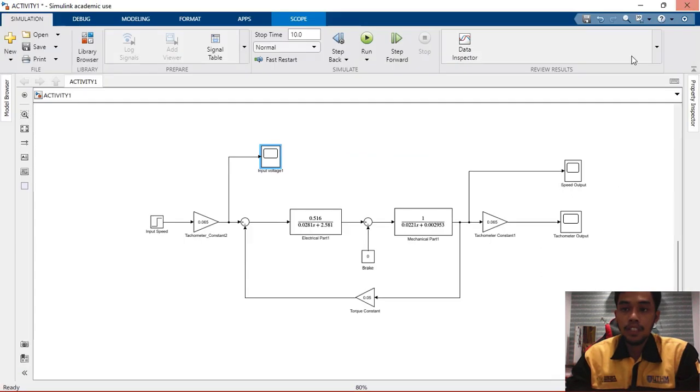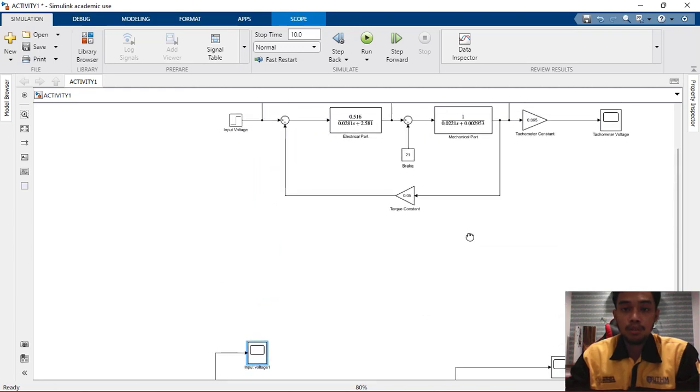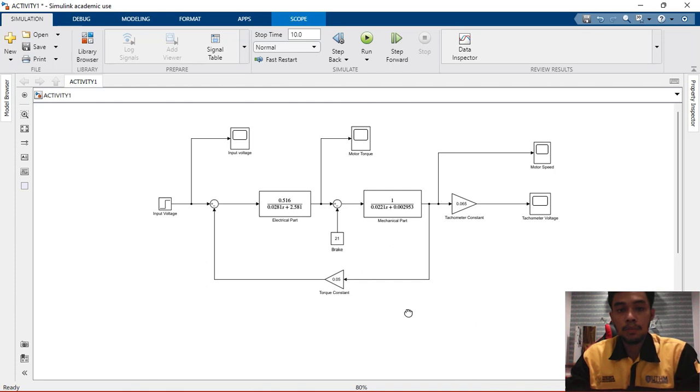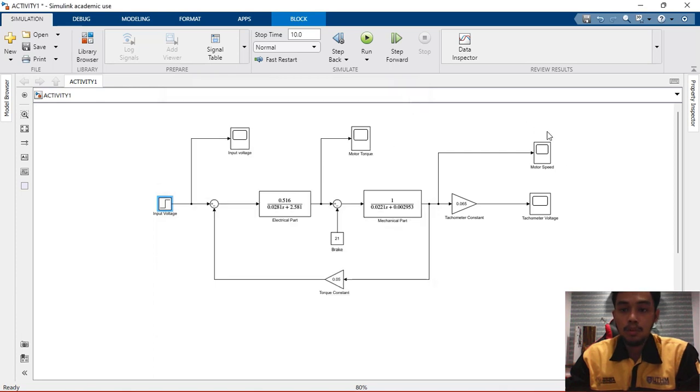And then after we obtain the input voltage value, we need to use the first block diagram for the open loop speed control system, where we use the input voltage that we obtained from the second block diagram, where we set the RPM to 2500, and this is the value 162.5. And then we need to obtain the motor speed by varying the brake scale from 0 until 21. So I will only use 3 values for this simulation.